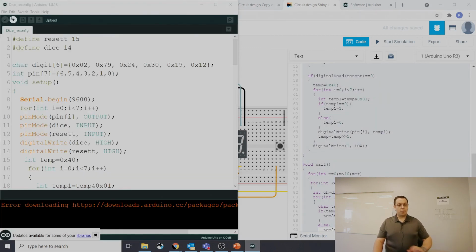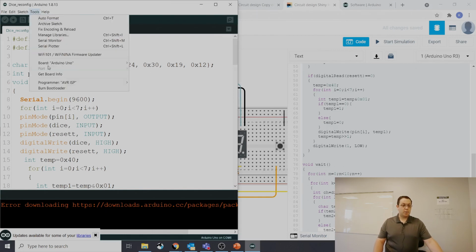We have our board built, we physically connect the USB connector, and then what we're going to get is, under Tools, the port is going to show up, and we're going to be able to select some port. It's going to probably be somewhere between COM 3 and COM 7, typically, and that's going to have the words Arduino Uno on it, and we're going to select that one.